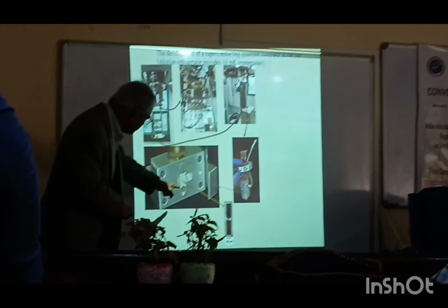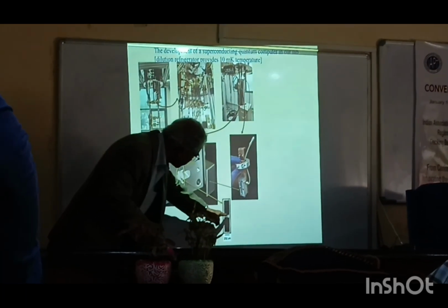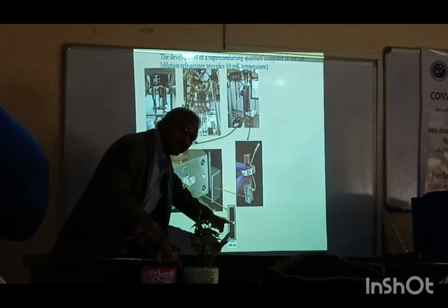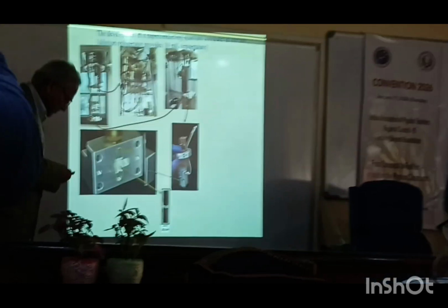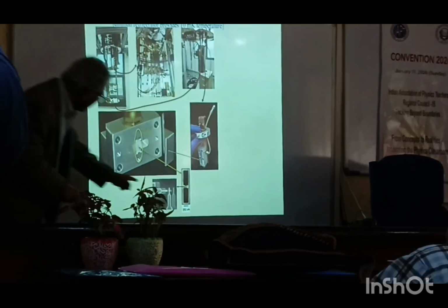It's magnified, this qubit. A Josephson junction is here, and it has its own parallel capacitors, and then an additional capacitor. And this is actually the Josephson junction. It's like an aluminum finger like that. It's oxidized here, which is an insulator, and then another aluminum finger. So aluminum becomes superconductor at that low temperature. It's superconductor, insulator, superconductor.